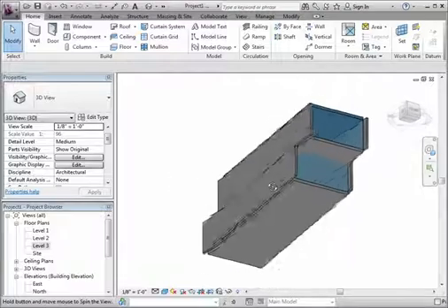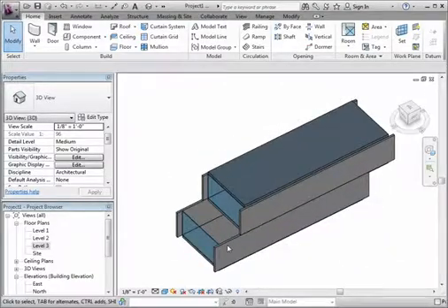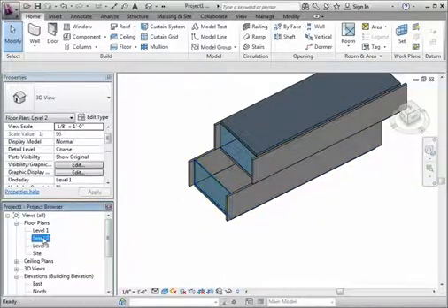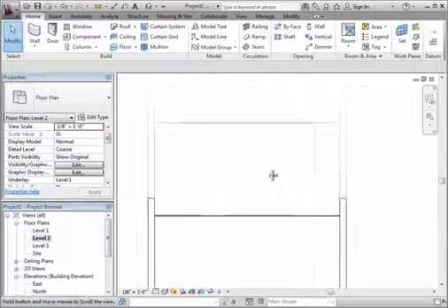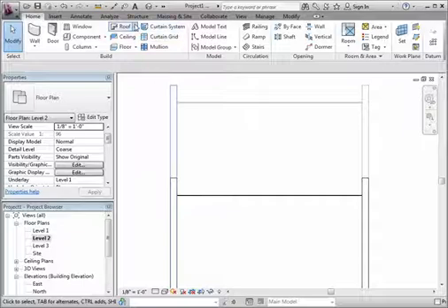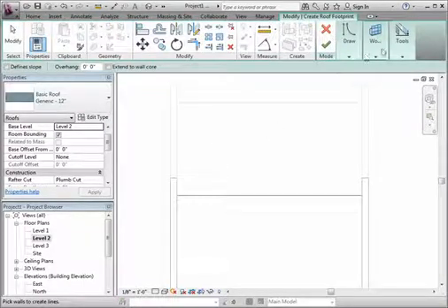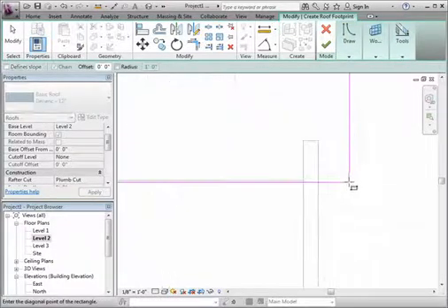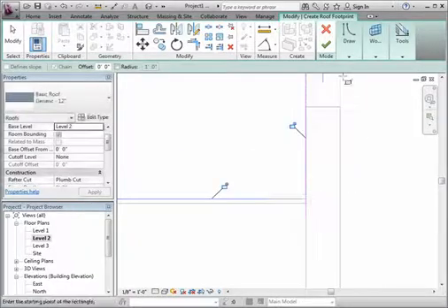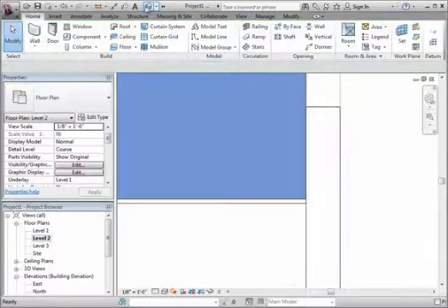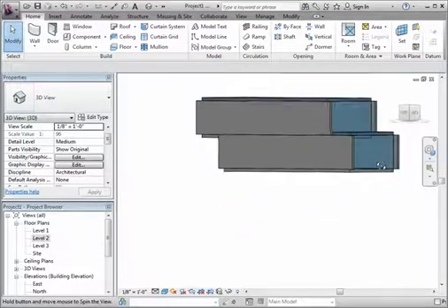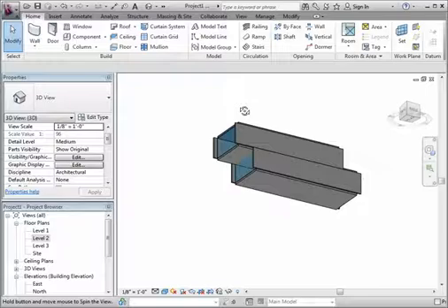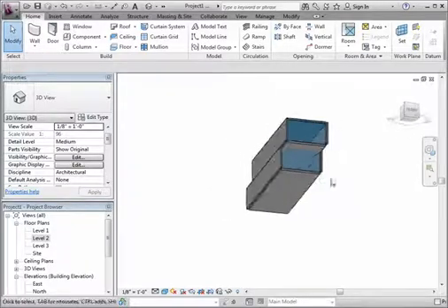All right, so let's see a couple things here. Number one, I'm missing a roof over here. So let's add a little roof onto that spot. I want to go to level 2. So I'll go to roof, roof by footprint again. Sort of the same process. Grab a rectangle. And then come to here. Give that a check. Go to 3D. So we have a roof. Of course, these are in the wrong places right now, but we'll fix that in a second. All right. So this is pretty close.